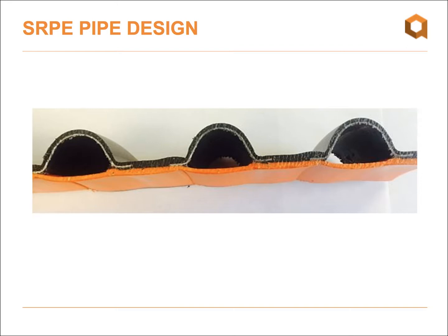When the outer reinforcing rib is brought onto the inner liner, HDPE has been heated past its melting point. So what happens here is a fusion process. It's not glued, it's not cemented, it's not welded, it's HDPE fused together past its melting point. So it's a very, very strong bond.